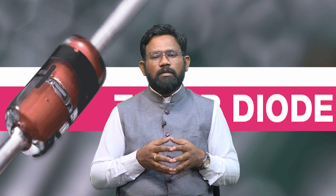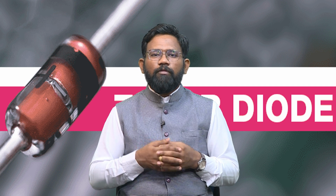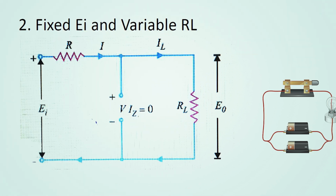Now, let us see the analysis of the Zener diode for the second condition. The second condition is fixed source voltage EI and variable load resistance RL. Here, one value is fixed, that is the source voltage EI, but the load is varying, that means the resistance across the load is varying. So, let us do the analysis of the Zener diode for this condition. The figure shows the circuit diagram where the source voltage is kept fixed and the load side is varying, shown by the variable resistance RL.